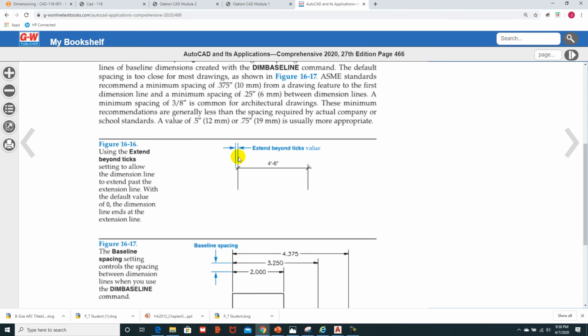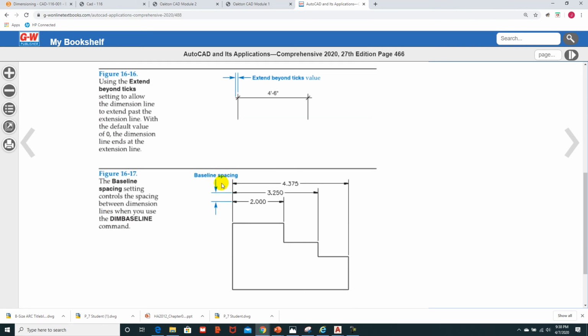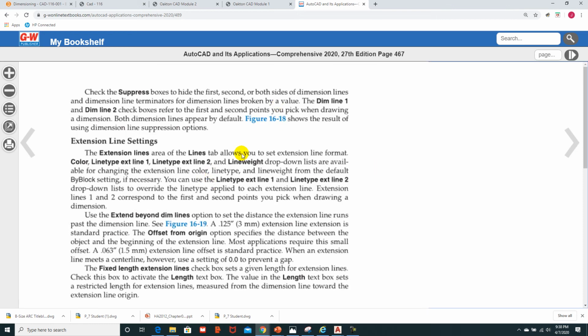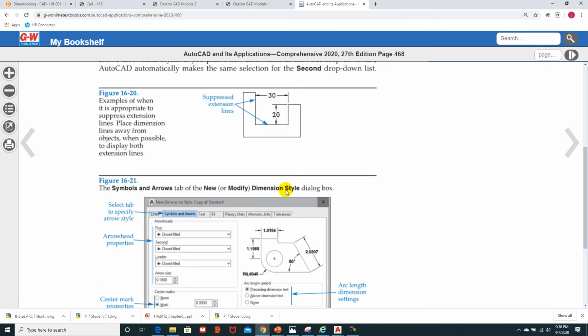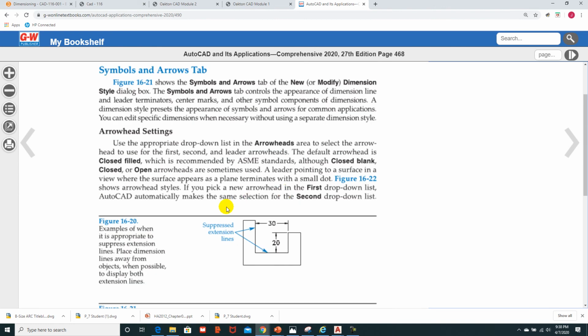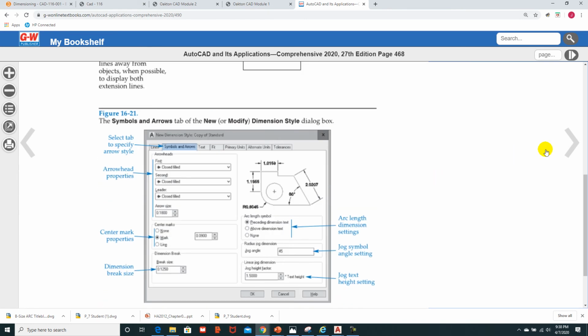And these are just sort of the small things. Extension lines, so there's just how to calculate the space between these. Most of your CAD managers will set that, like we did for you, in the title block. And so we'll give you a standard dimension style like we have done on the architectural title block and on the B-size mechanical title block. And so I don't think we need to go through every one of these details, but it's a great reference as you start to look into it and you're saying, well, how do I do that dimension style?